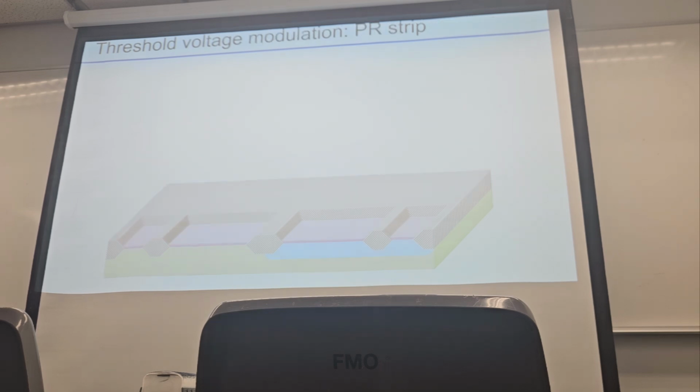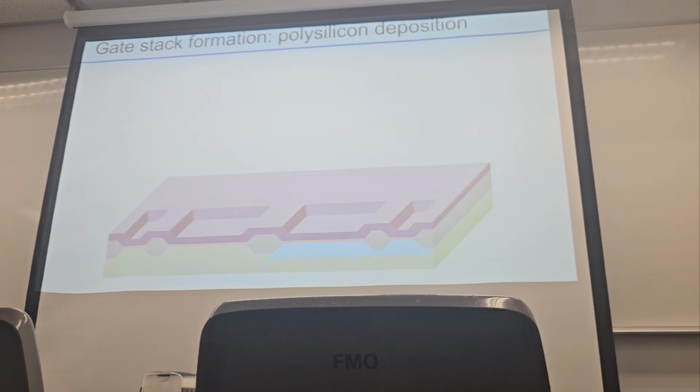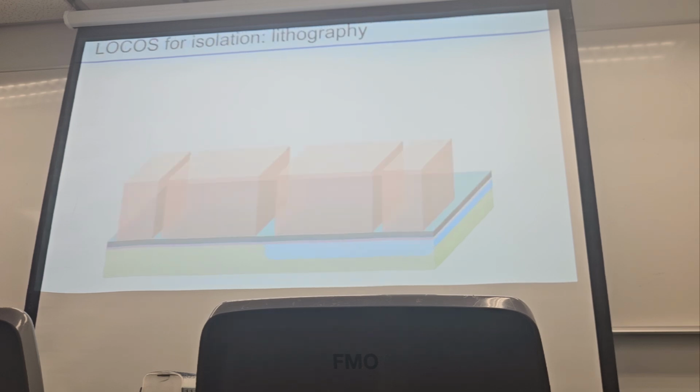Okay, so then we can remove the silicon dioxide to reduce the oxidation. You can see we can do different types of silicon dioxide, different steps of silicon dioxide thin film formation for different purposes. Then the next step, we can use the polysilicon deposition. Before, you can see that all these oxidations are based on thermal oxidation, not CVD, because we want to have a good quality.